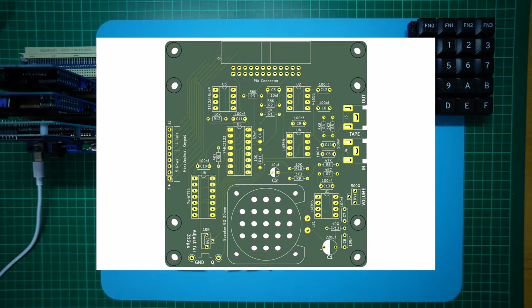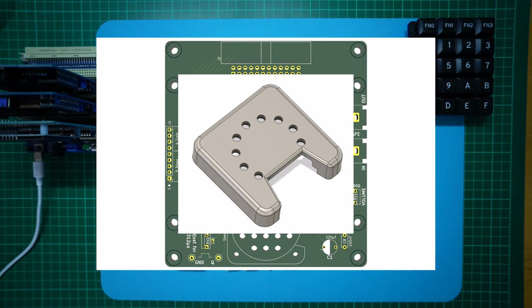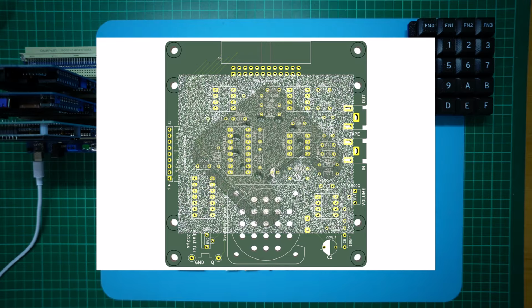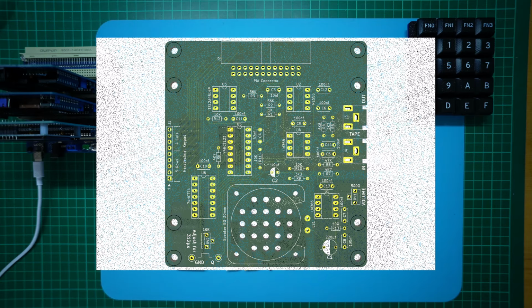You simply connect the resultant module to the MECB Motorola I card's PIO port in the same way as my earlier implemented Creative Vision Recreations controller board. Then you just have the two RCA connectors at the side to connect to a tape deck for a realistic retro experience, or for connecting to a PC sound interface. For the speaker mounting, I've also created a 3D printed speaker shroud, which nicely holds the speaker to the circuit board. So next, let's get one of the new interface cards assembled.